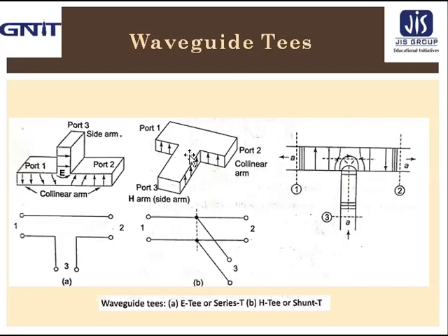That's why an H plane junction is called a shunt junction. For a symmetrical and lossless junction, in the absence of nonlinear elements at the H plane junction, the S parameters are obtained in a similar manner as in the case of the E plane junction.